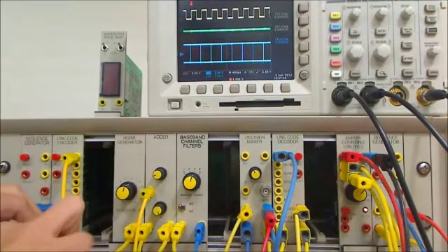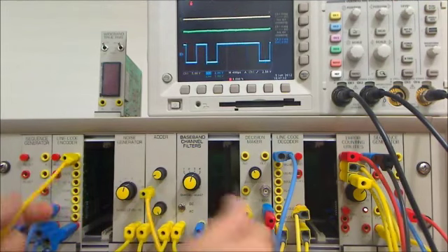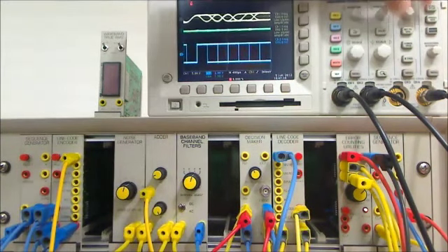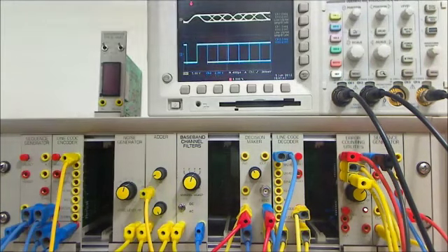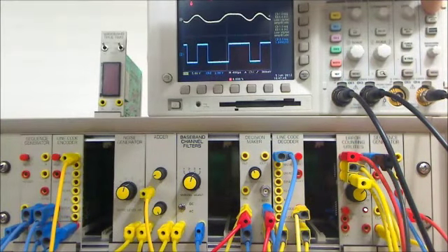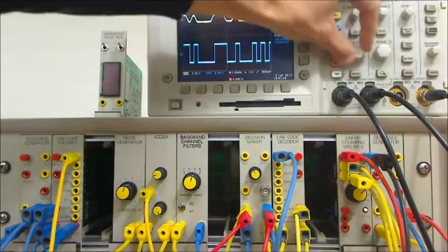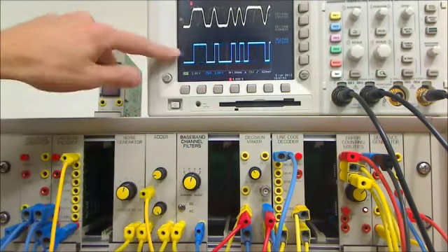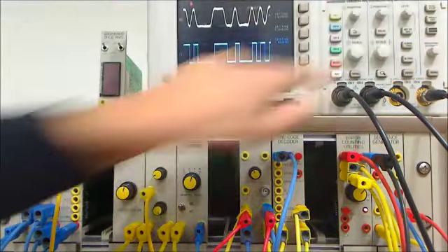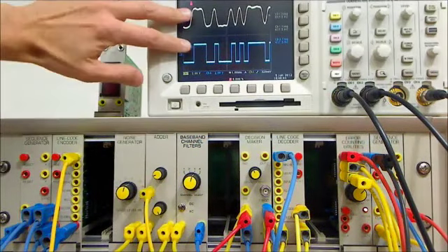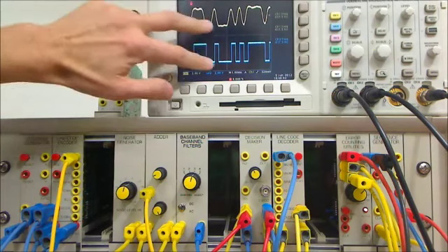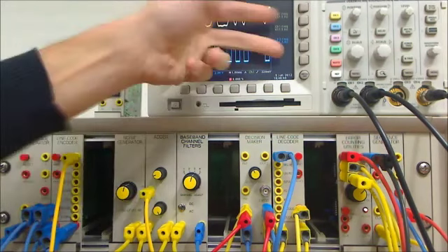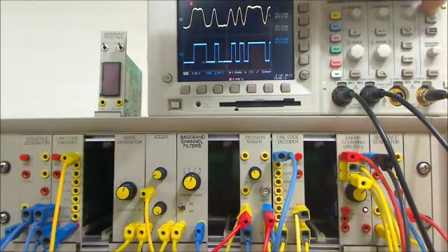Okay. Now we'll try to use both of our channels on our scope to look at the clean signal out and the input. Turn off the signal. Use single shot. At the top we have the band limited input, and at the bottom we have the output from the decision maker. You can see they correspond: 1, 1, 1, 0, 0, 1, 0, 0. And without any significant noise, the correspondence is there.